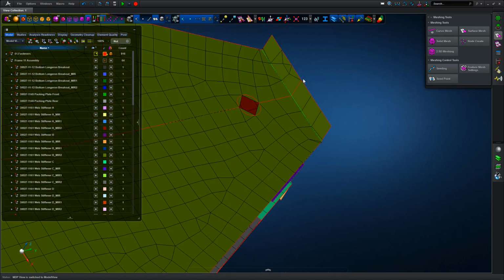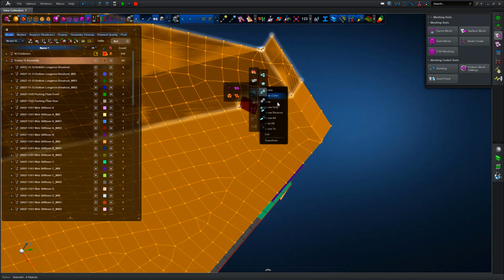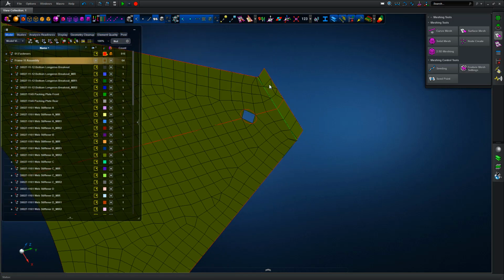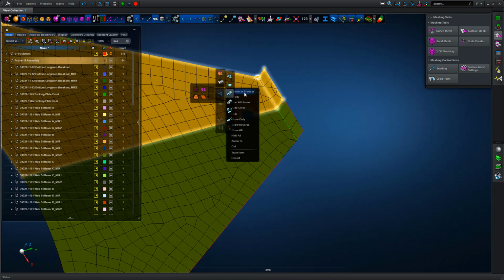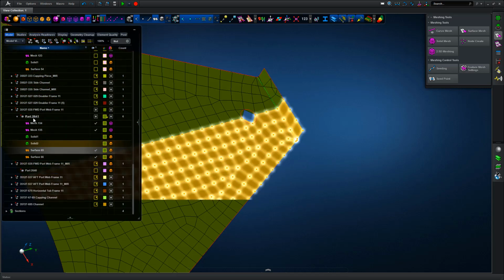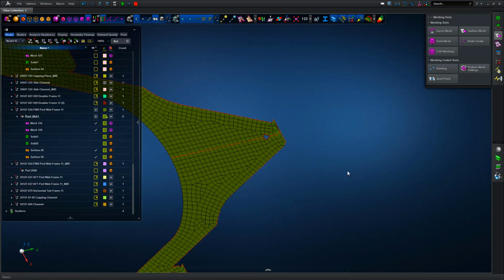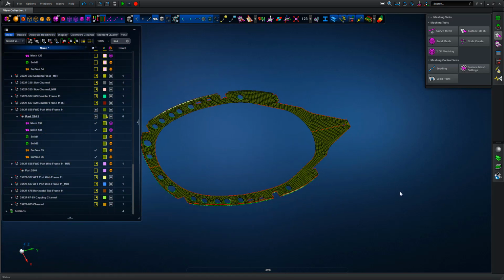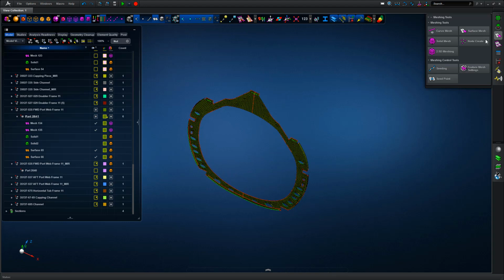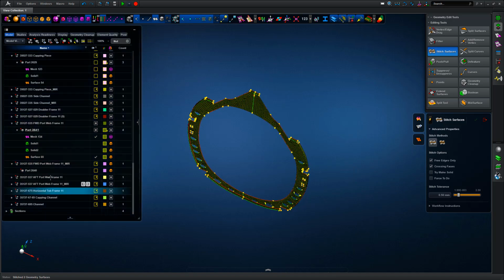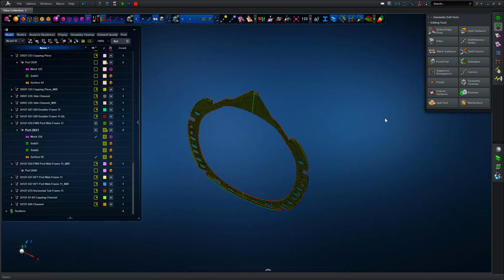So what we're going to do now is look at one particular area of interest, the green surfaces that we picked out earlier. If we centre in the browser, under that part we have two solids, two surfaces and two unique meshes, and the red line at the interface between the two surfaces shows that they're not currently stitched together. So we're going to stitch them, and then we can see in the model browser tree we now have a single surface and a single mesh for that representation.